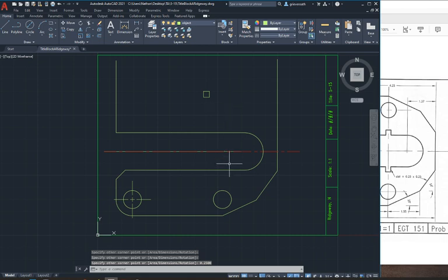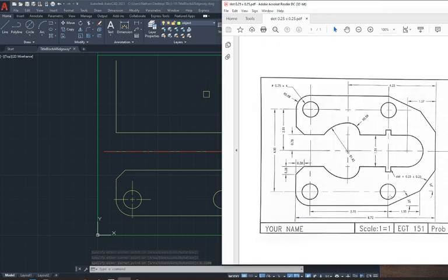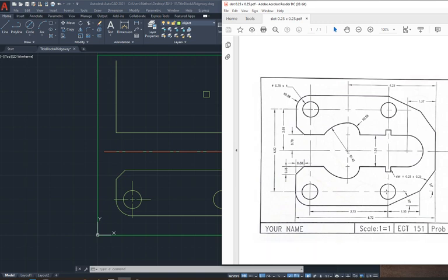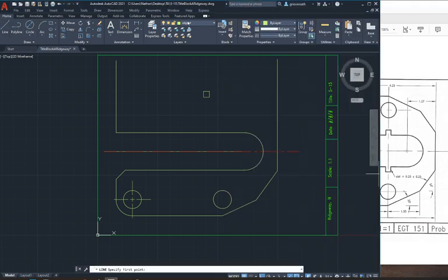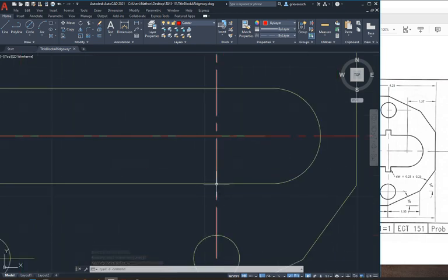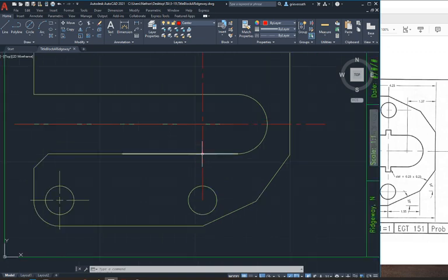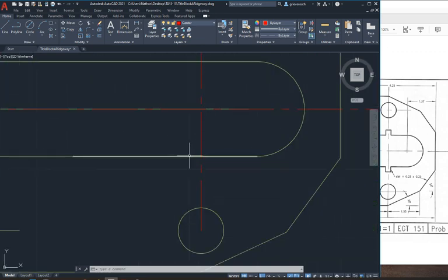That is our square. Now, where does the square go? Well, as we can see, this is centered due to this center line given right here. This is centered on these circles. So if we take a line, let's just throw on a center layer, why not? And we mouse over it, it'll give us the center to snap to, and we just turn ortho on and go all the way up, escape. I know the center of this square is aligned with this center line, and that the wall of this square is basically touching this wall here.